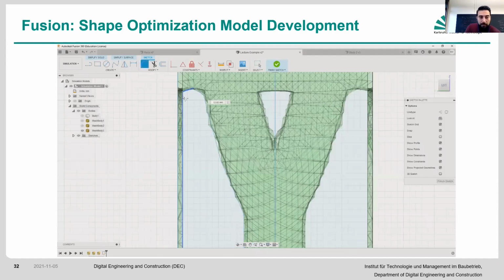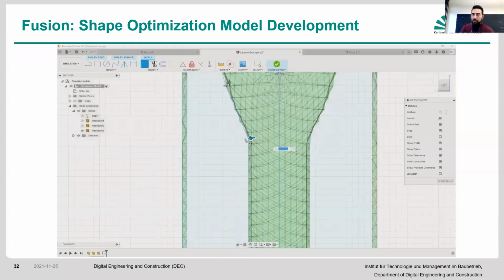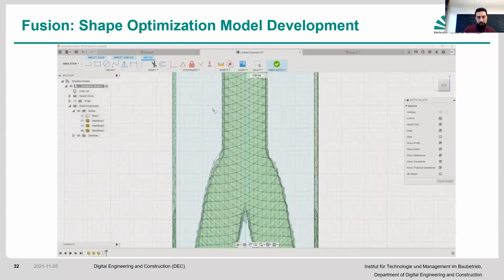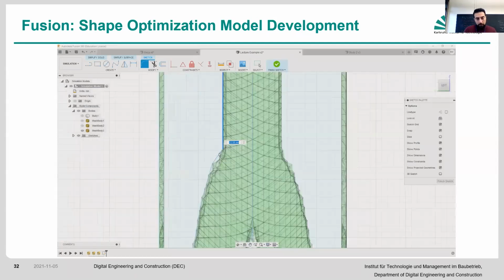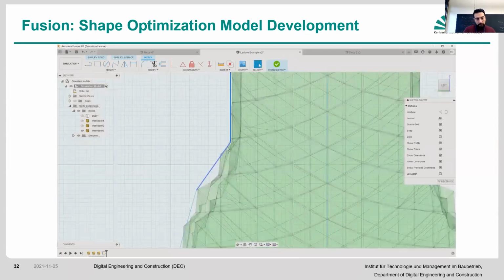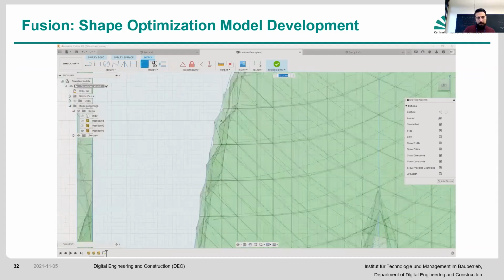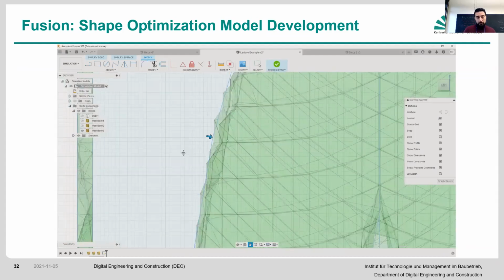And then you go with the fillet. You essentially do it between every two. Again, I emphasize that this is to minimize the propagation of cracks. So in every element, it's good for us to have, instead of very sharp edges, kind of a curvature there as well, and minimize the stress concentration. Here, the other thing is that once you do those and you have those fillets, you can actually go on top of it and play around with it and actually change the dimensions of those fillets as well.